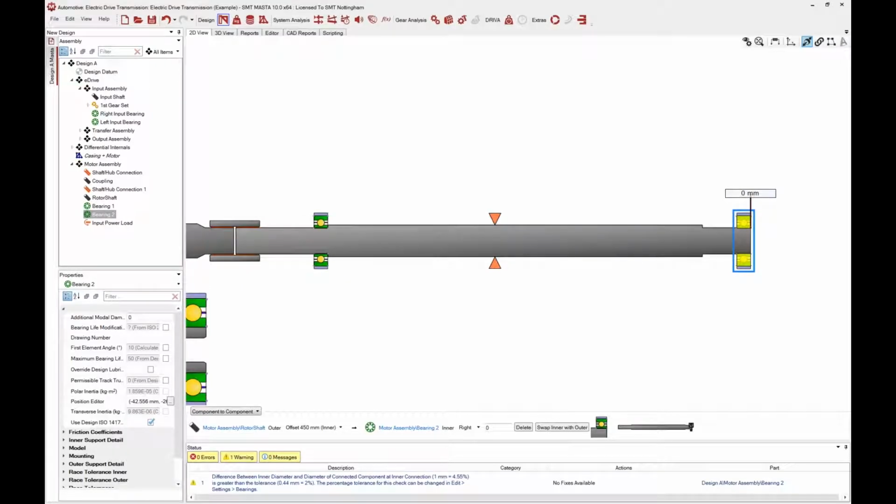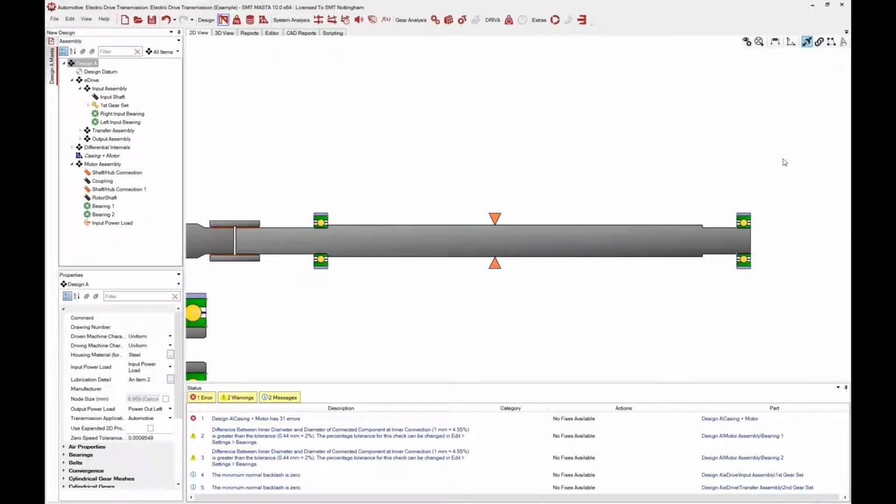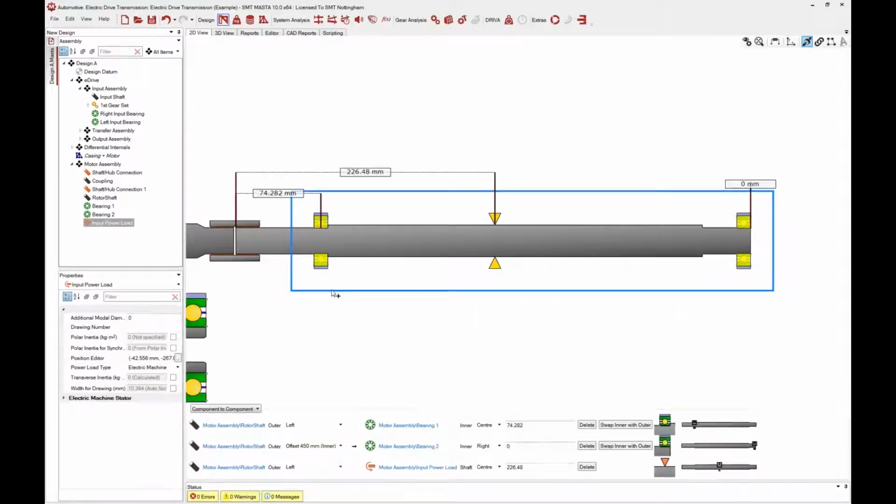You should also be aware that you can multi-select options in here as well for movement. So the same way as you would in sort of Windows Explorer window or something like that, where you can multi-select files, you could just multi-select items in here. So we can box select by holding down Control. So if I hold down the Control key and drag over a bunch of items, anything that's completely encompassed within the box I create will be selected and can be moved as one, so their relative positions won't change.